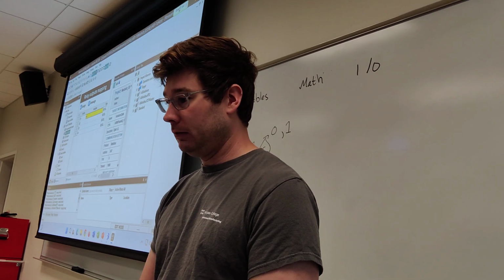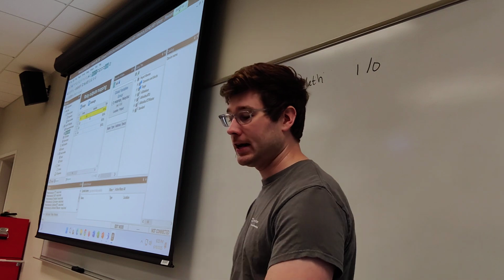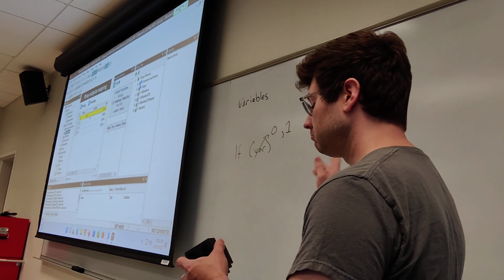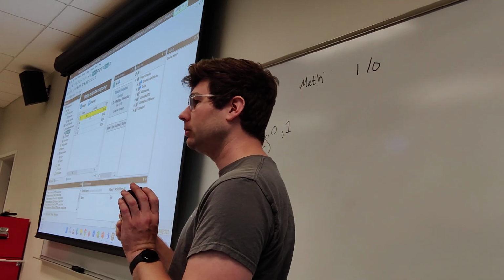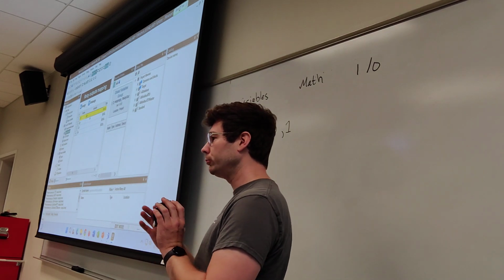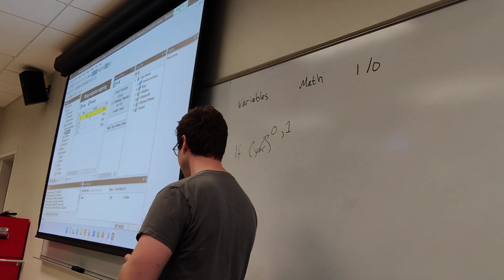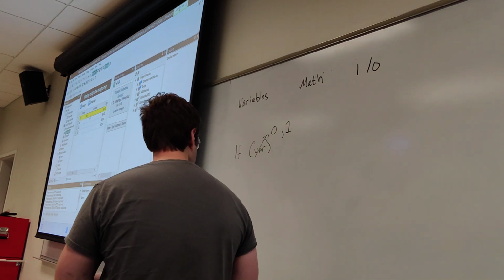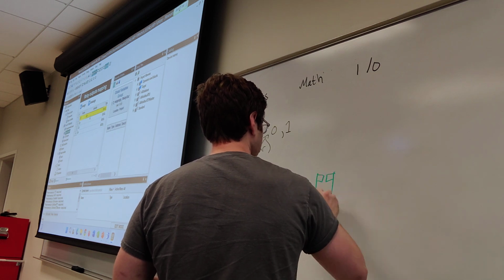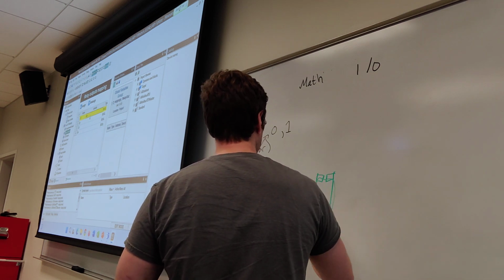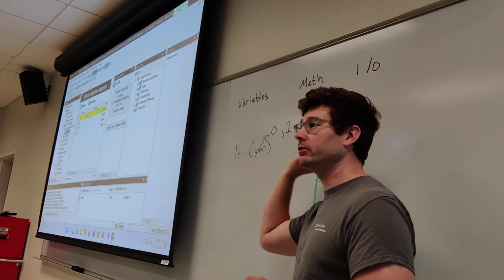Say I have a motor or a fan that's going to kick on. I have it attached to my first relay. It's a 120 volt fan, so I've got 120V coming in on this terminal. It can be AC, by the way. Relays can do AC or DC. It doesn't really care. One of the cool things about relays is that unlike transistors, to the electricity they just appear like a strip of metal. They have no problem shooting across there. It doesn't care if it's AC, going forwards, going backwards, doesn't matter.